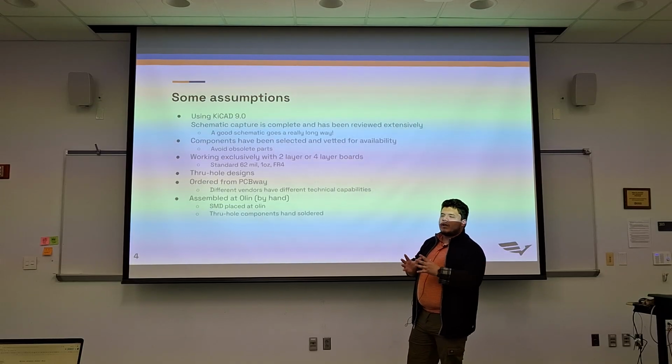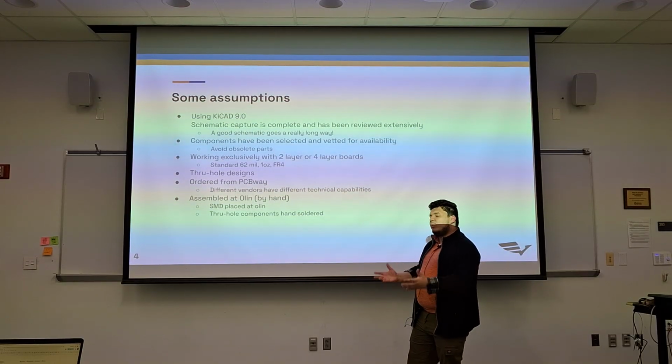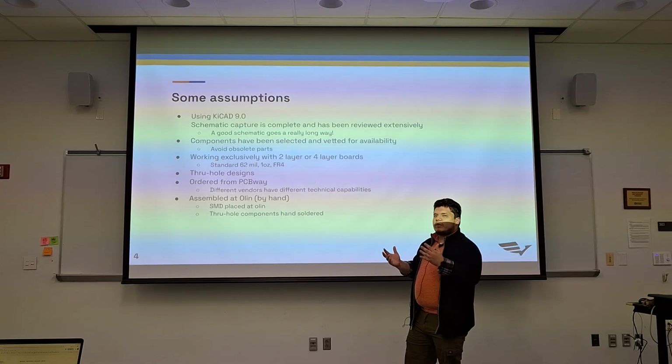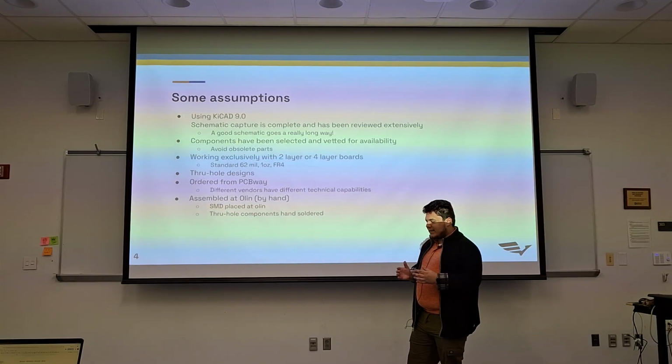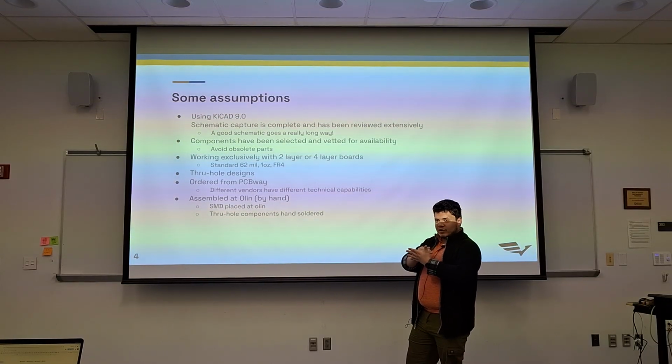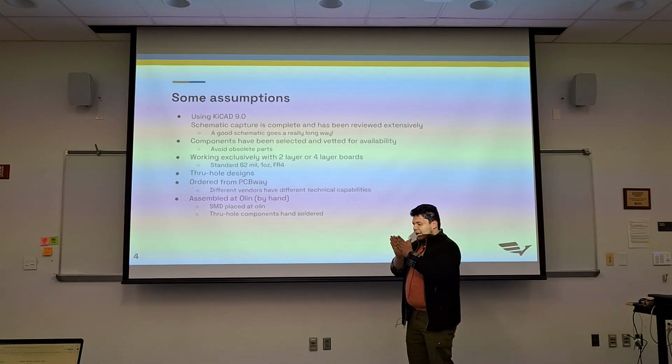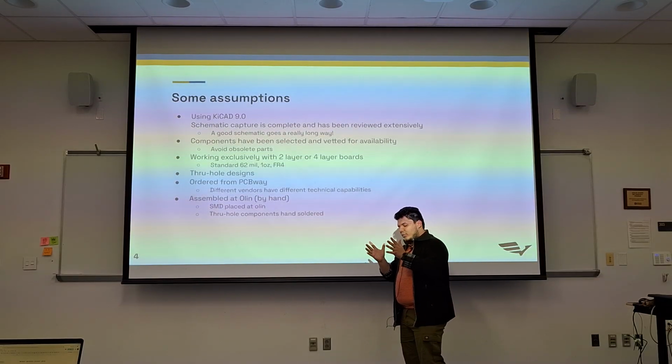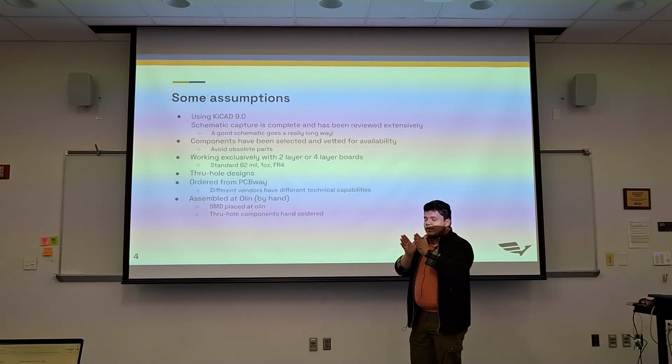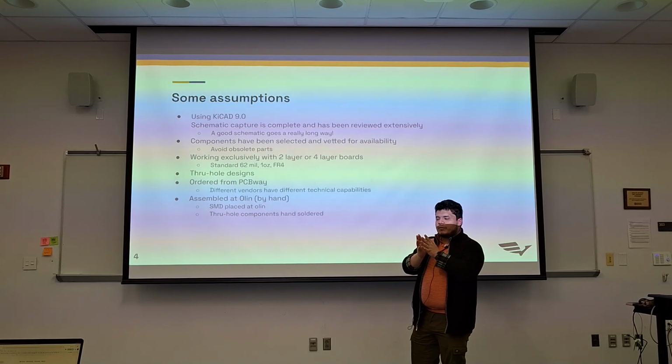Generally speaking, whenever we talk about PCB manufacturing capabilities, we always want to be way above that. Because whenever we're talking capabilities, that's like the bare minimum, like in an emergency. If we can't make a lot of room, like if we have to route tightly, that's where you have to depend on the minimums.